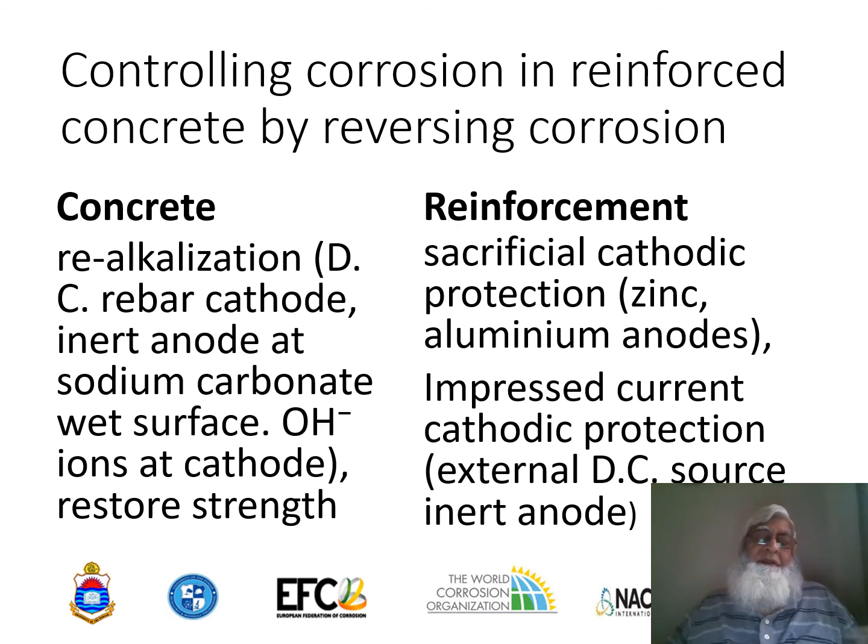in the alkalinity, or the loss in the pH, is restored and re-established, right? So hydroxyl ions at the cathodes help in restoring the alkalinity, and the process is called realkalization. And if possible, the strength of the concrete can then be restored by repair methods.